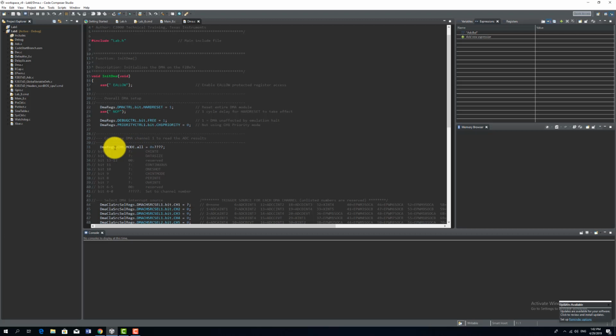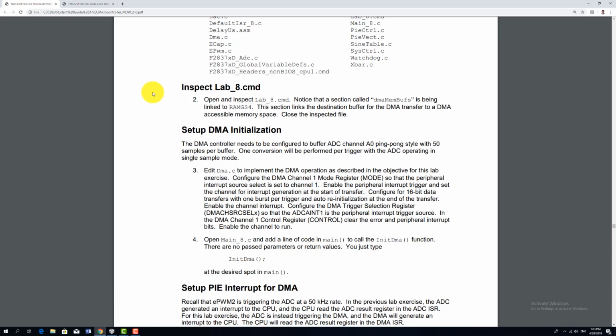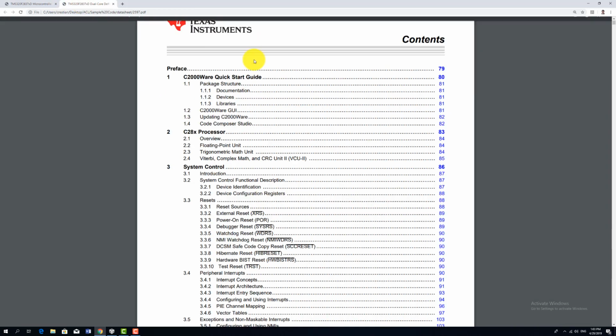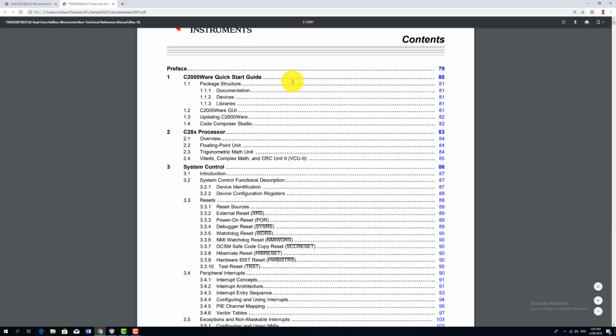This value here, we cannot just simply check or define without basing it on the datasheet. So we have to go over to our datasheet by simply copying the device register. So we have to copy this one, the DMA regs, and let's proceed to the datasheets. So you have here Control F and then Control V.